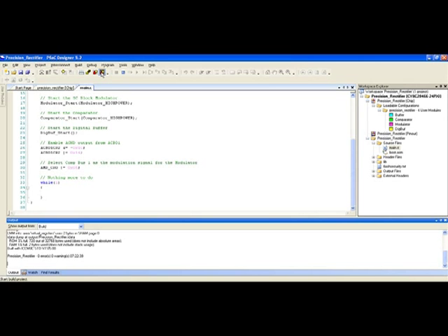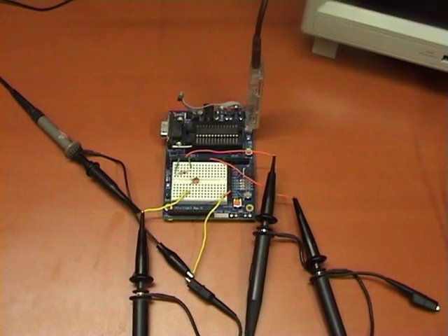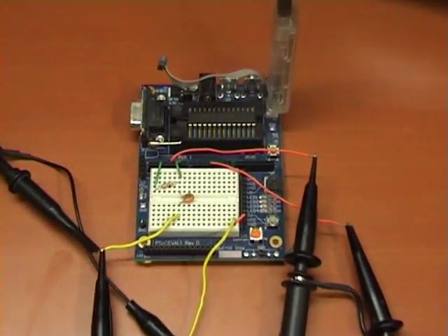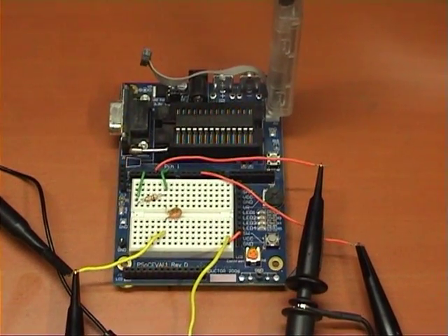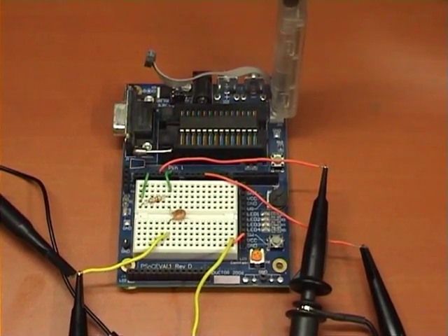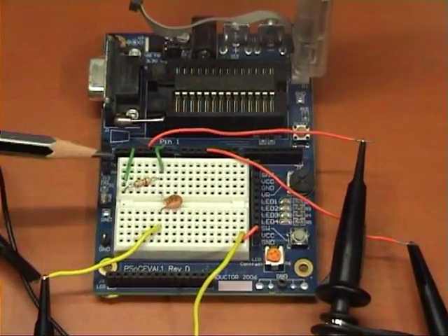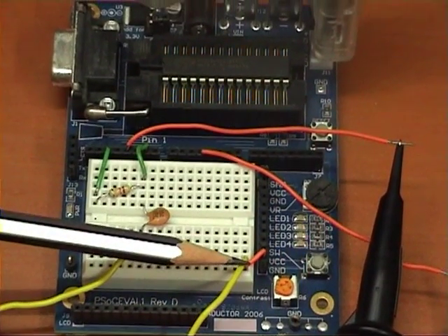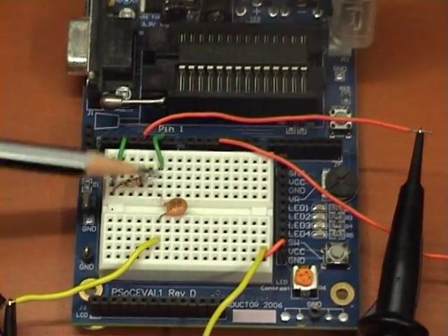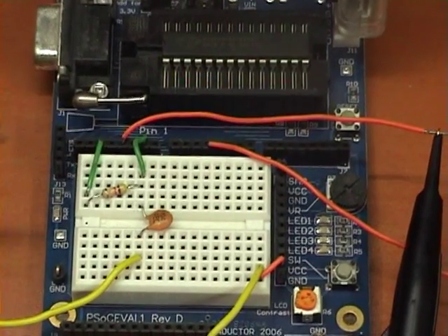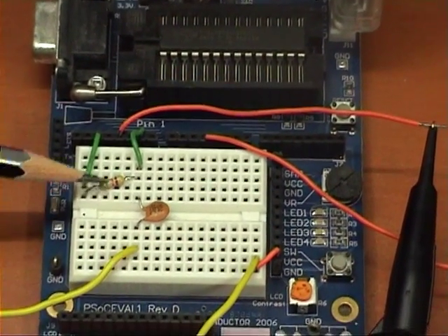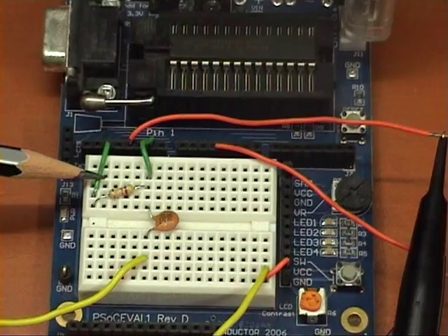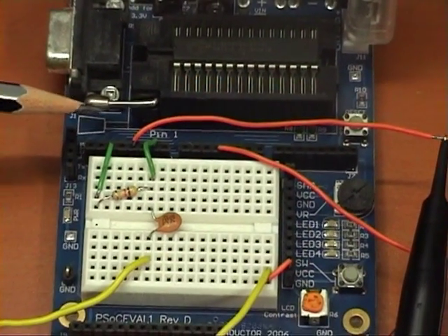Before we program the PSoC, let us have a look at the hardware setup. We are going to use the CY3210 PSoC1 evaluation board to test the project. The input signal from a signal generator is connected to one end of C1 with respect to VSS. The other end of C1 is connected to port 01. R1 is connected between port 01 and the analog ground on port 05.